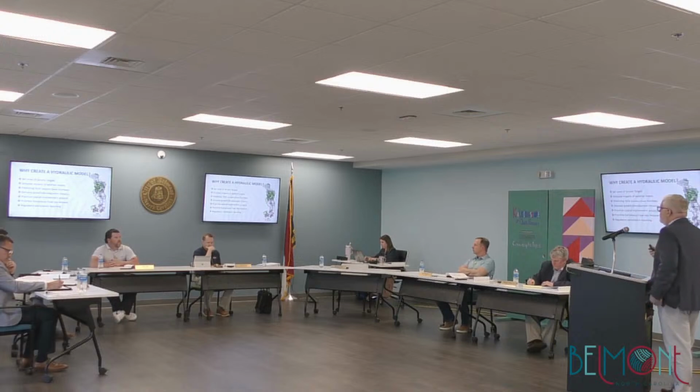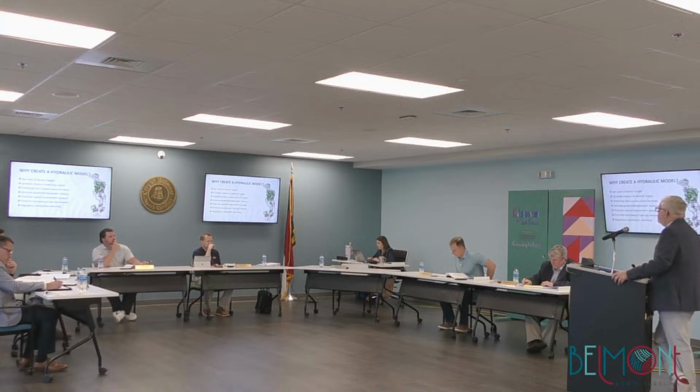The other thing is we're going to talk about weather events, meaning rainstorms. And I'll describe those as 2, 5, and 10-year events. And one of the great things with this model is that we can simulate those types of storms, how that affects the sanitary sewer system, how new development affects the sanitary sewer system, and so we can give you an idea of what those impacts are before experiencing those.